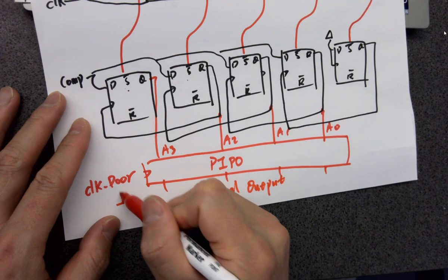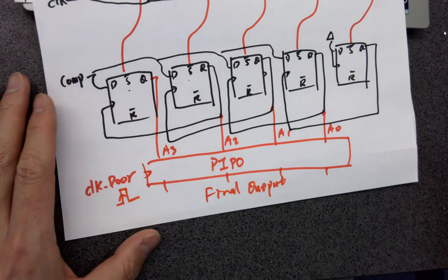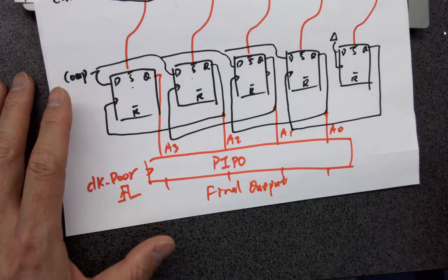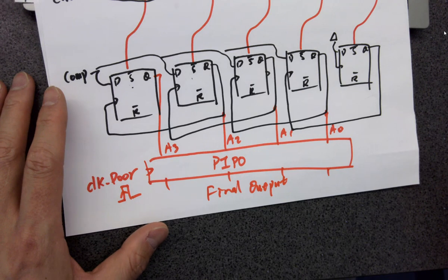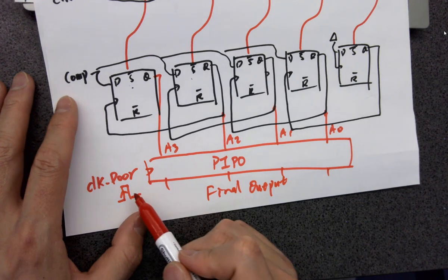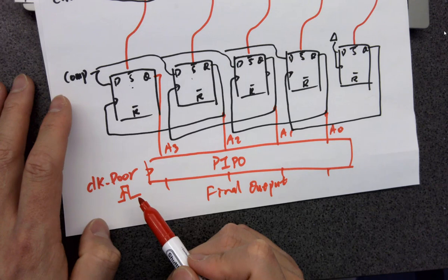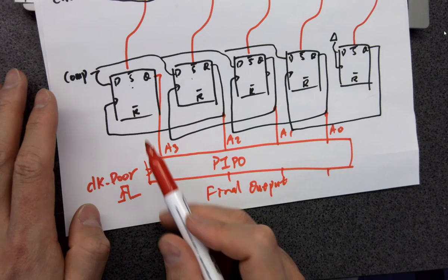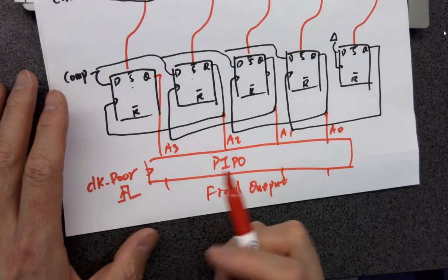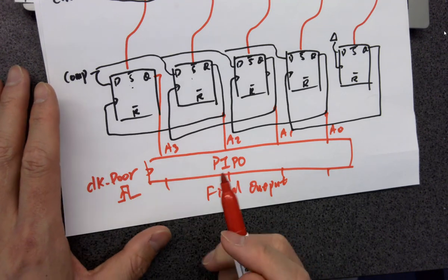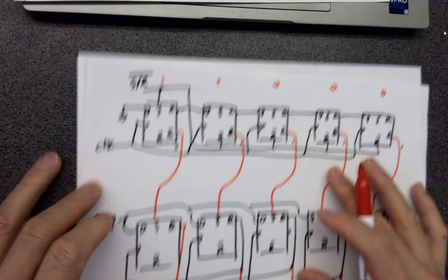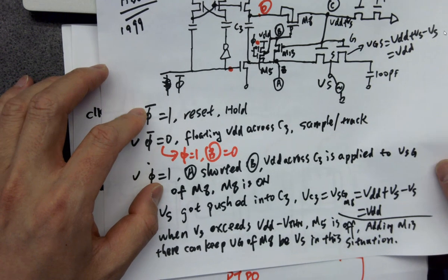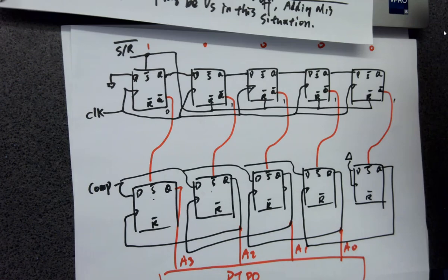So there will be a rising edge here. Why is it the rising edge? Because we are using the same D flip-flops, and that D flip-flop is the rising edge D flip-flop. Whenever the rising edge arrives, you just need one little pulse to make it happen. So you can imagine if this is an 8-bit ADC, you need 9 different states, and you need 2 dips in front of it to set it up. So eventually, there are a lot of things to consider.